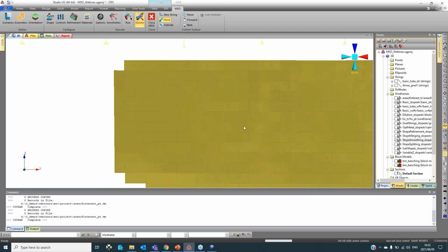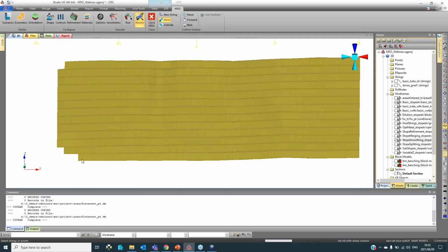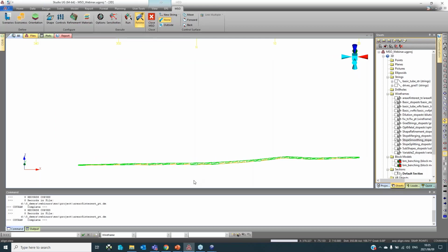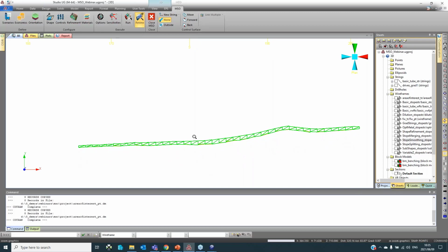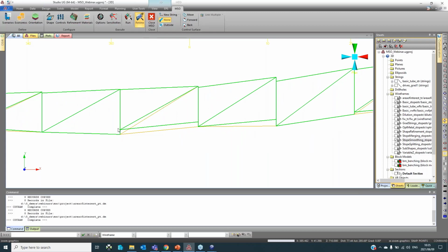The other scenario is the stope smoothing, that tries to remove the corner between 2 different stopes. So if I use this section here, and we go to that area, for example. See, the green ones are the original ones. They have these corners here, the sharp ends. And the yellow is the smoothed. It just goes from here to there, refining that difference between them.